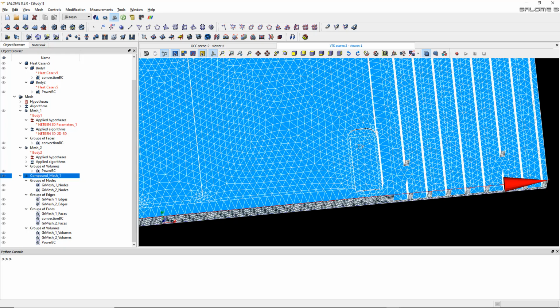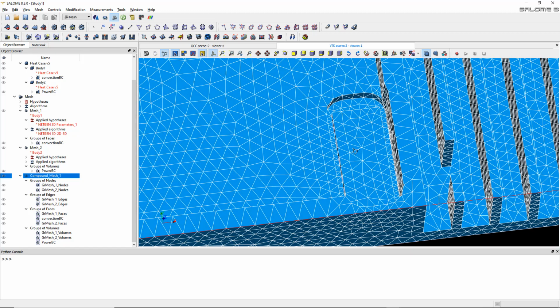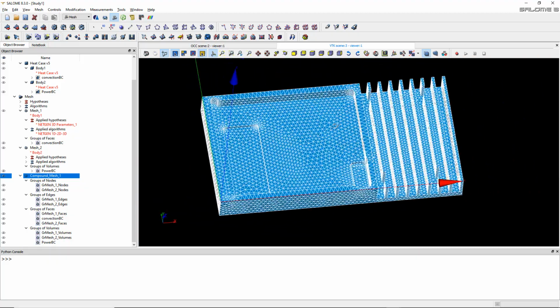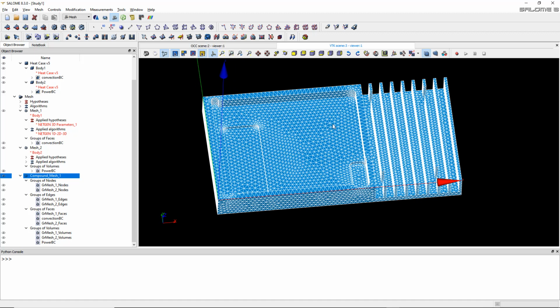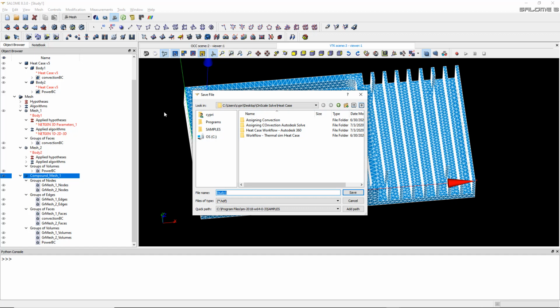But in this case, because I meshed those separately, there are very few chances that the nodes on the side there will be the same as the nodes on here. So what I'll do is use a specific type of thermal contacts in the solver that will basically do the trick. So I don't care if those nodes are not merged together. Okay, and now don't forget to save.